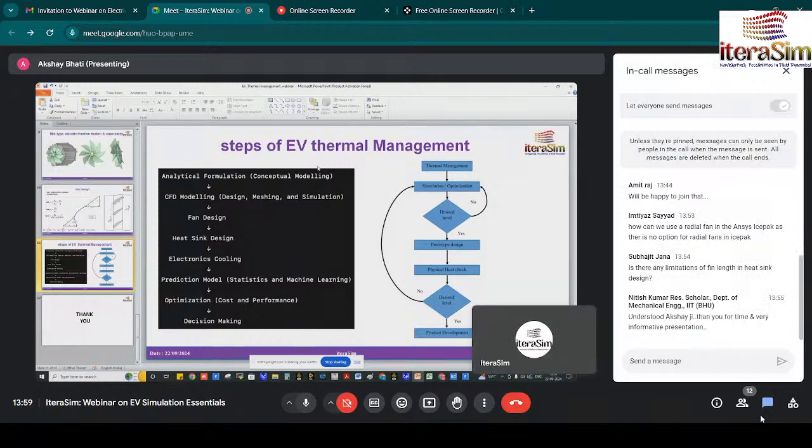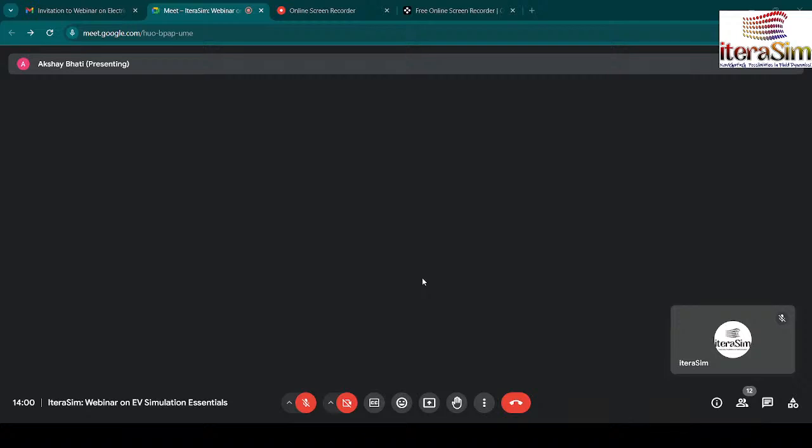If you think about an electrical motor fin, it has a different fin length. And a heat exchanger would have different length and thickness. So it depends on the application. And basically if you increase the fin length, obviously up to a certain level the heat transfer rate will increase, but after a certain level it will not increase, because it will reach equilibrium. So it depends on how much flow rate, what the temperature condition is, and up to what length it will come into equilibrium with the flow.